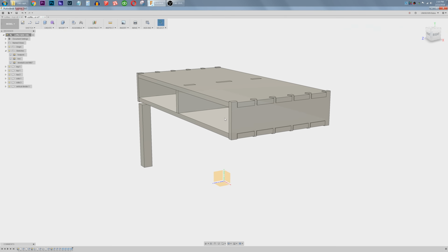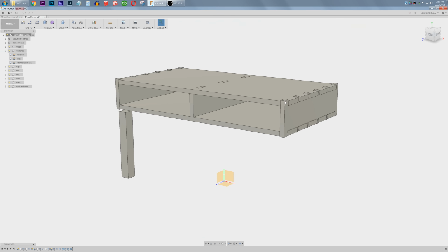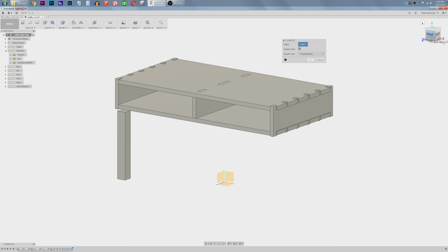I want to take this a step further and I'm actually going to chamfer every single one of these. And if I was to do a chamfer in SketchUp, holy moly, would that just be time consuming and crazy and insane. Not so much in this, it's really cool. Let's go to modify, chamfer, and let's make sure we are on an orthographic view. So we are looking dead straight amongst all of our lines, and go to a front view.